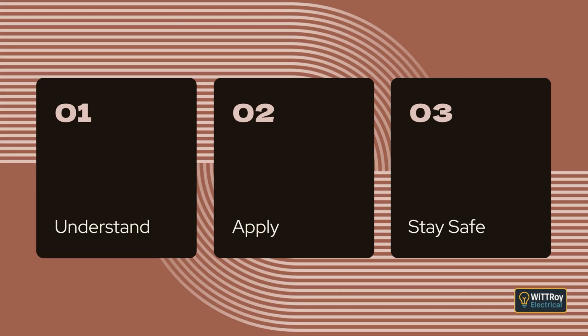Next, the path of the cable must be drawn on a plan so future workers can find it. That plan must be kept at the switchboard where the circuit starts. For consumers' mains, the plan must be kept at the main switchboard of the building. If the underground wiring is fully inside a building area, marking is not required.